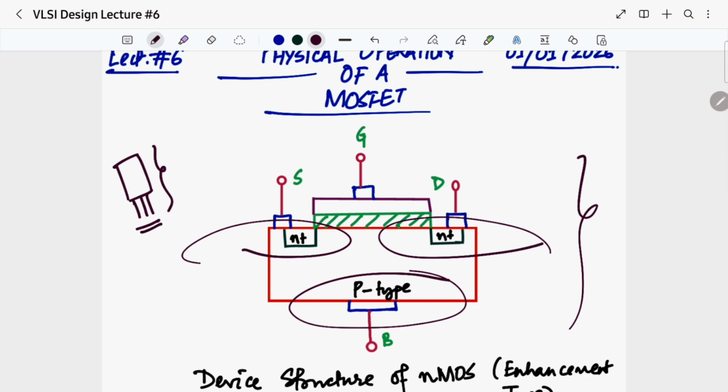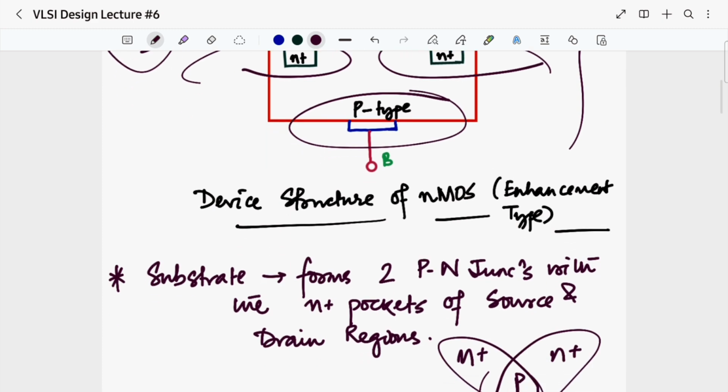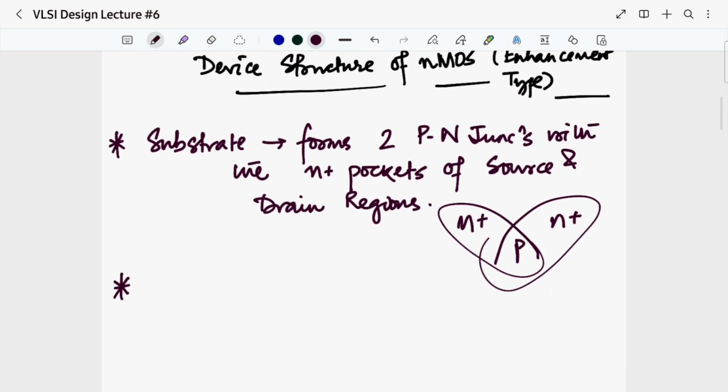You will only see 3 pins, but we have discussed that a MOSFET is 4 terminal, and in the device structure also we can see it is a 4 terminal device. Then why does the actual MOSFET that you will be using in your analog labs have only 3 pins? That is a big question, isn't it? Suddenly one terminal cannot just go poof in the air, isn't it?